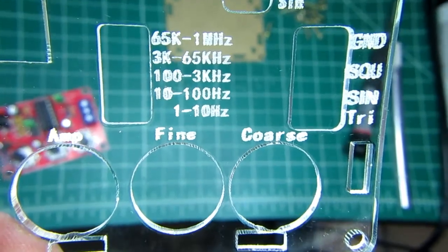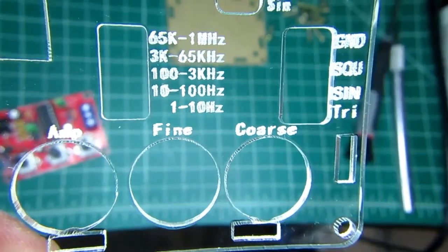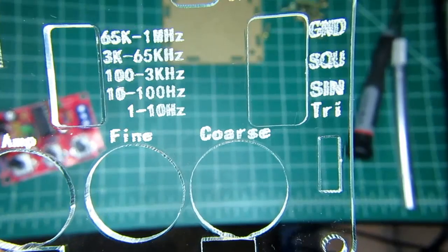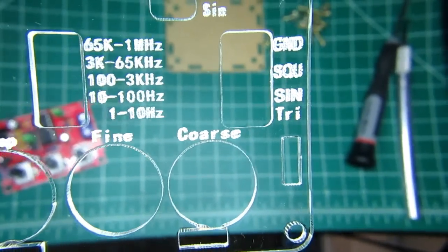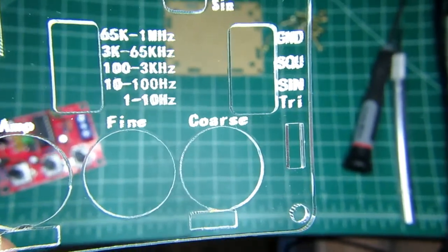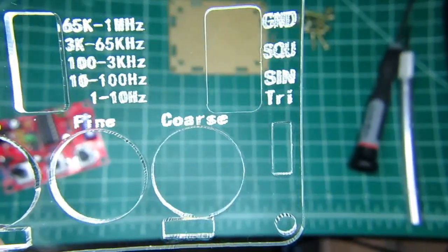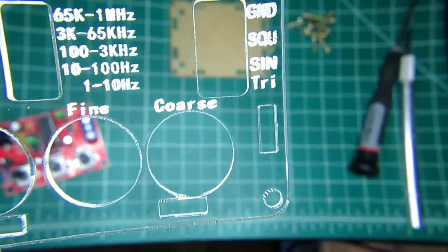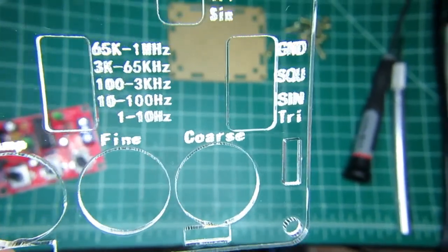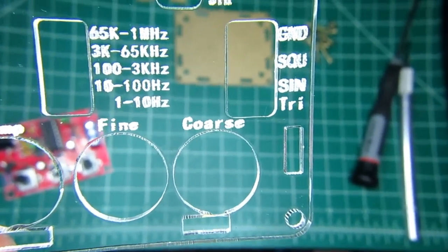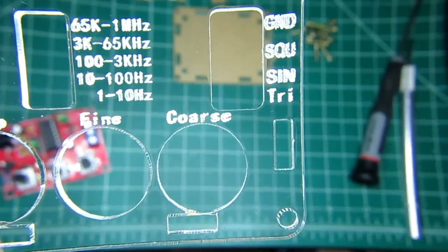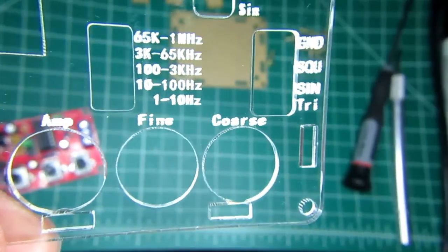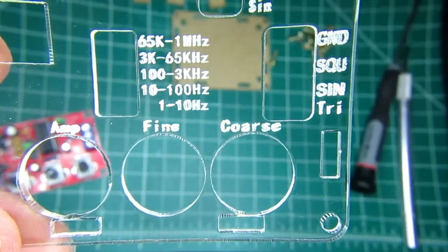I carefully picked away at the back side of these engravings with the tip of my X-Acto knife, and even though it's still sloppier than I've seen a lot of other laser engraving, it's definitely more legible now, having picked all those little tiny pieces of paper out that were stuck on the inside of zeros and in the crevices of ends and things like that. So that's worth doing if you build one of these.